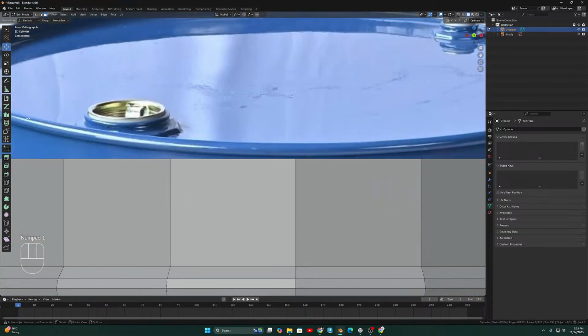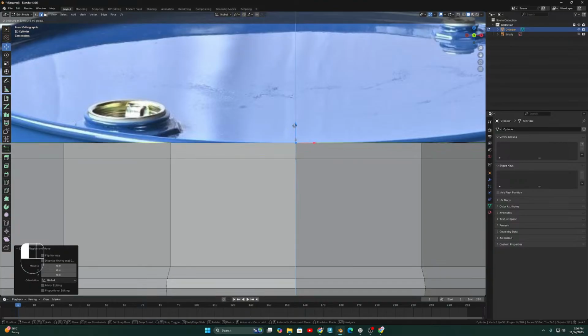Again I will go to front and select this edge, press 2, go to edge mode, select this edge, and then E is the shortcut to extrude. Click and I will move. Why do I click? Because I wanted to move it in one axis.